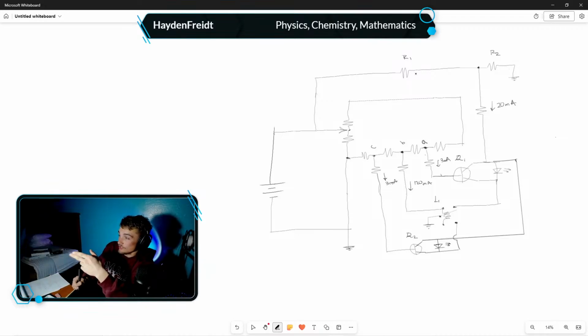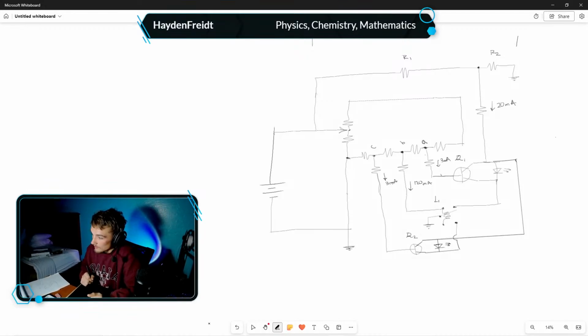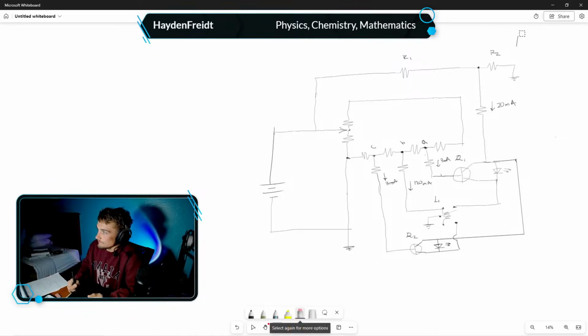So these two resistors are in series, and so it's a voltage dividing circuit. We're gonna have a voltage drop across him and a voltage drop across him. These two resistors are in parallel with the battery. So that means that this entire thing, from here to here, is also receiving 9 volts. I wanna get rid of those lines. Okay, so now that's important because